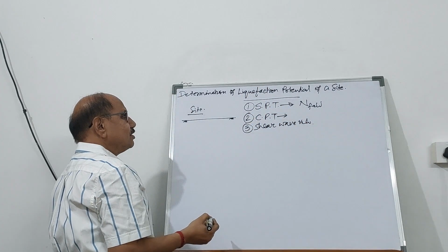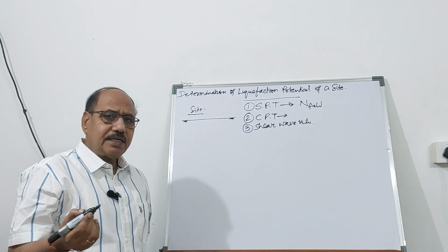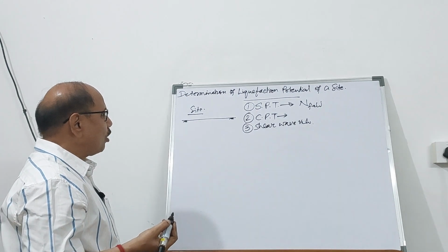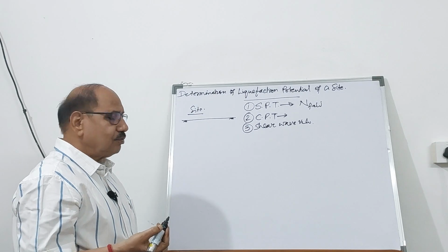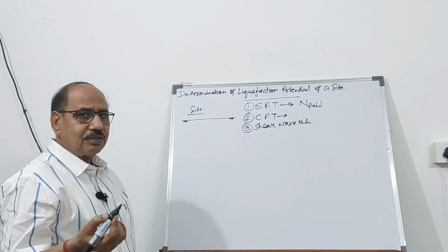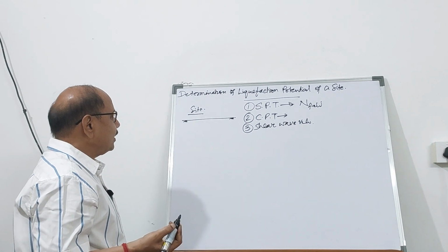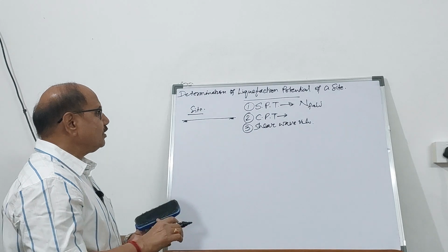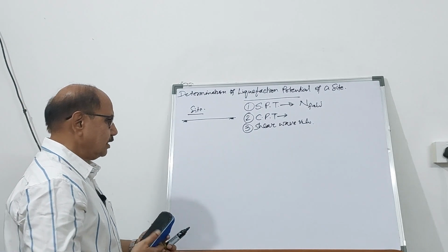So these are the tests, and IS 1893 part 1 2016, they have come out with a simplified approach which is based on Seed and Idriss technique, his research paper. So today we would like to highlight the Codal provision for determination of liquefaction potential of a site.